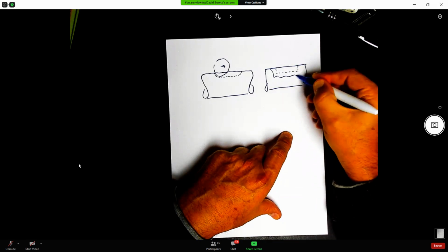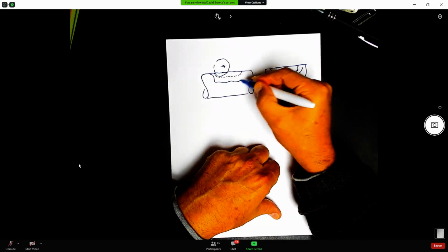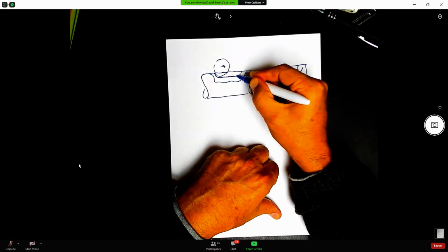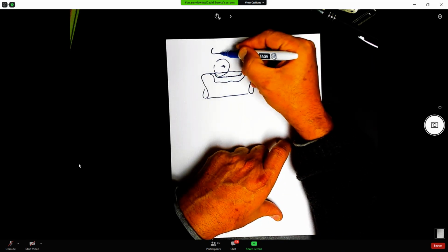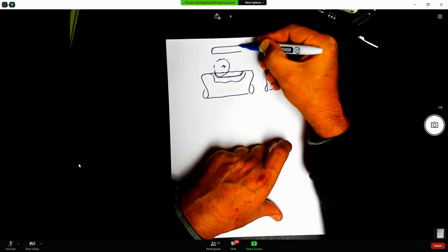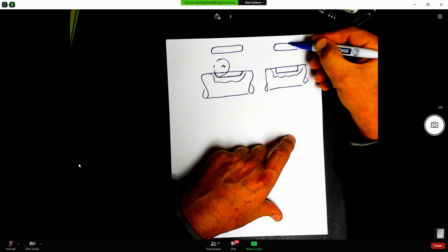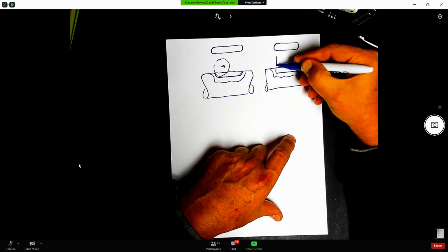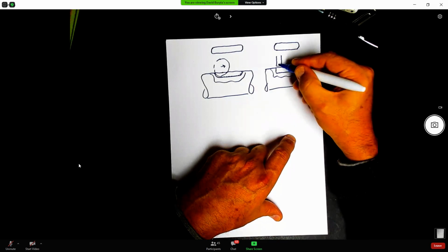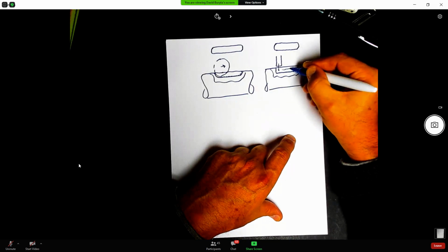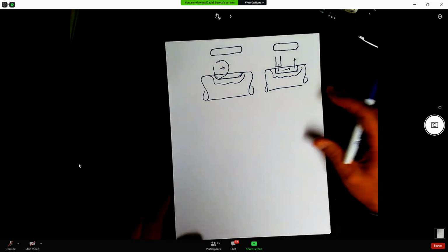Or if we do a broken out section here, from the top they both look the same. From the top, this looks like this, and from the top, this looks like this. They look the same from the top view. This one's cut with an end mill, or what some people call a center cutting end mill, so it can plunge directly in, move along, and then come back out here to cut the keyway into the shaft.